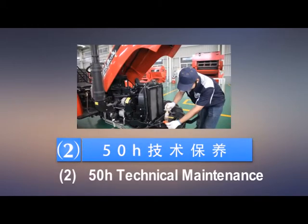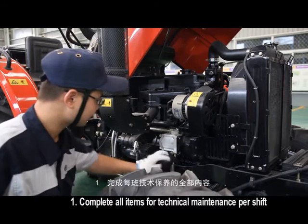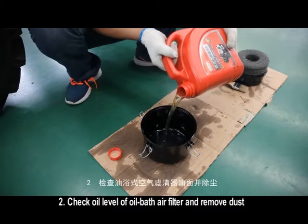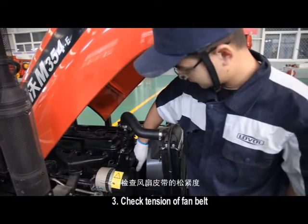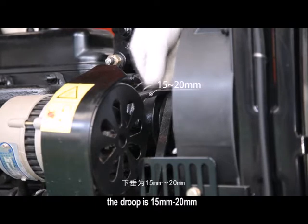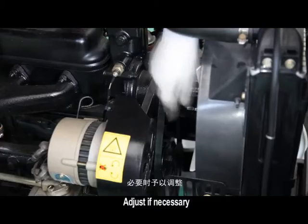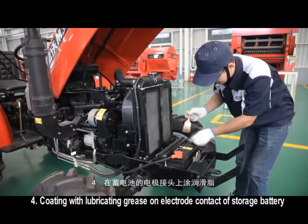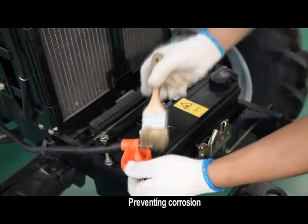2. 50-hour technical maintenance. 1. Complete all items for technical maintenance per shift. 2. Check oil level of the oil bath air filter and remove dust. 3. Check tension of the fan belt. When pressing the belt, the droop is 15 mm-20 mm. Adjust if necessary. 4. Coat the electrode contacts of the storage battery with lubricating grease, preventing corrosion.